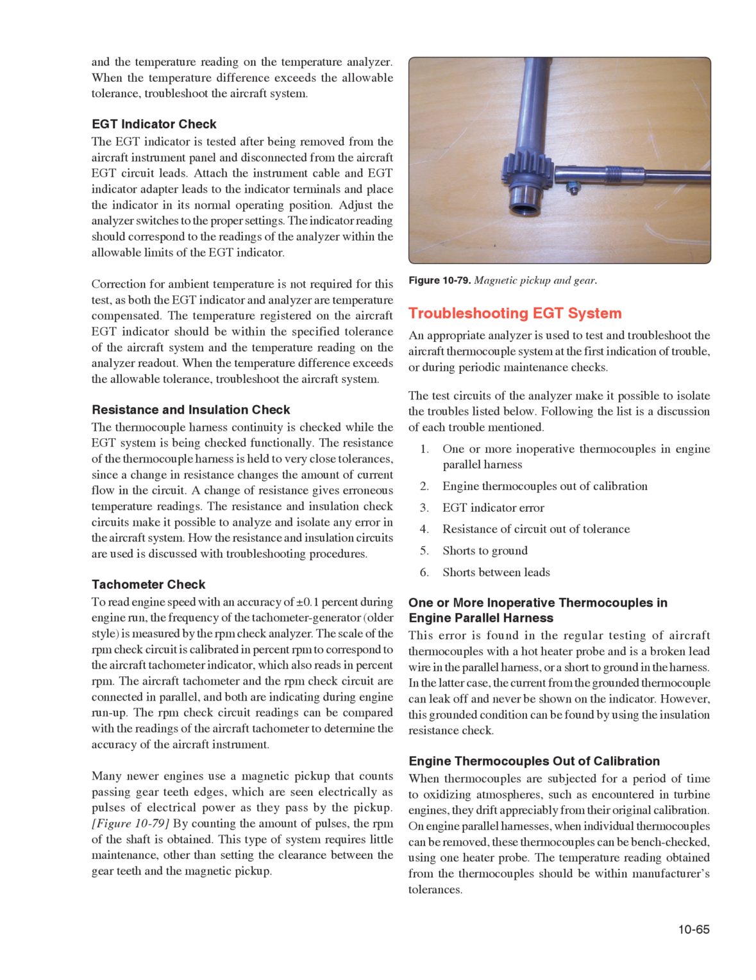Troubleshooting EGT system. An appropriate analyzer is used to test and troubleshoot the aircraft thermocouple system at the first indication of trouble, or during periodic maintenance checks. The test circuits of the analyzer make it possible to isolate the troubles listed below. Following the list is a discussion of each trouble mentioned. 1. One or more inoperative thermocouples in engine parallel harness. 2. Engine thermocouples out of calibration.